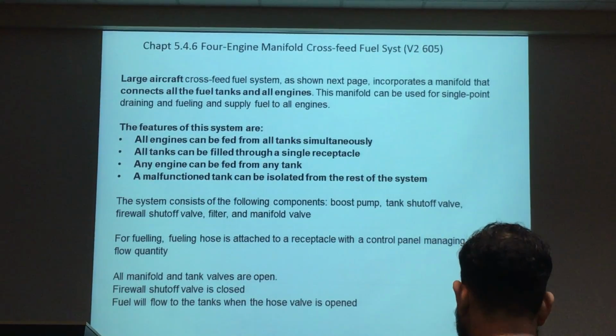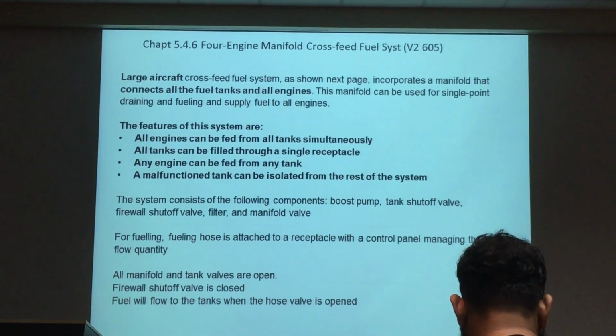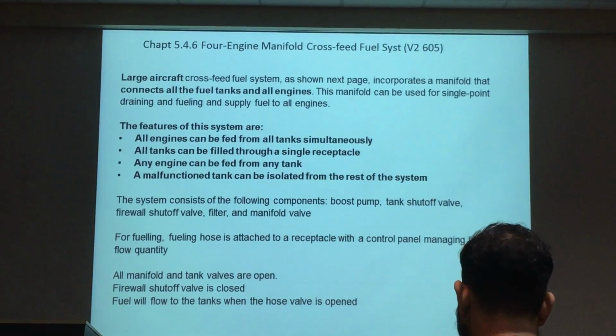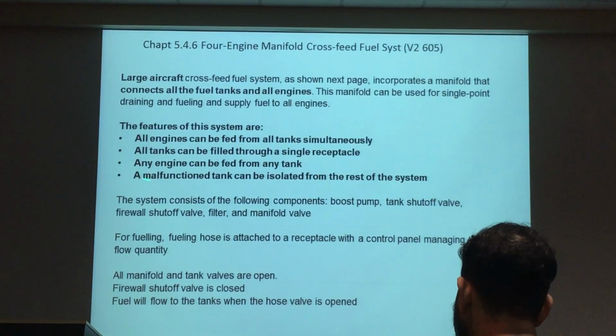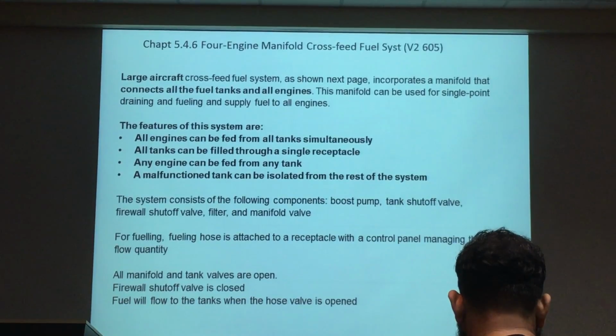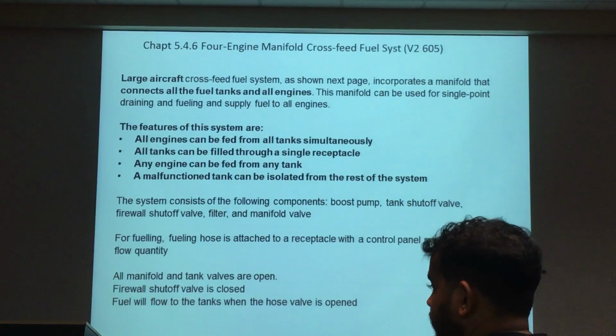If this tank, the fuel pump system fails or something is wrong, you got to isolate the tank. Yeah. The next step is to think about the fuel remaining inside. You need to think of a way to transfer the fuel out. Okay. But for the basic level, you need to have these 4 features. If you want to be a designer, you better know about these 4 features. Okay, these 4 features, in between your topic 5 to topic 6, your fuel tank to engine fuel, these 4 features must be there.